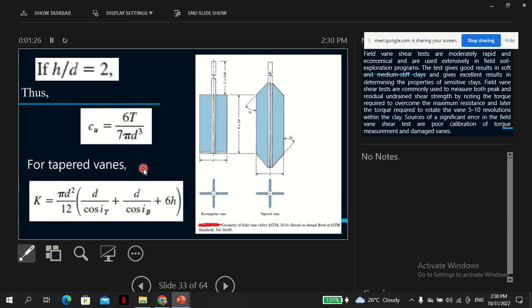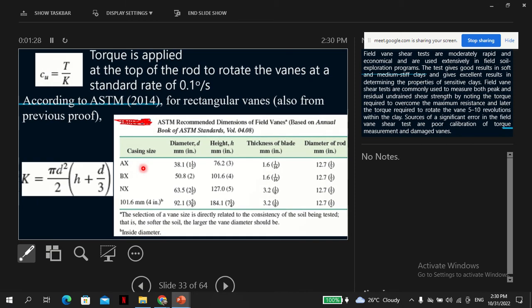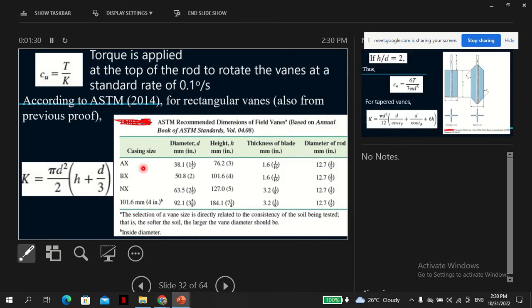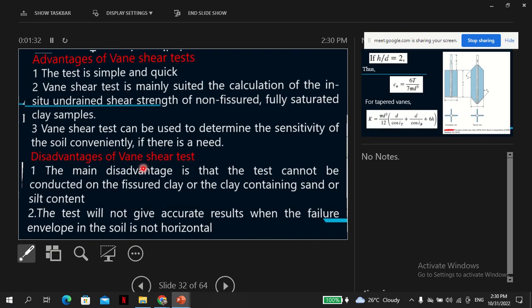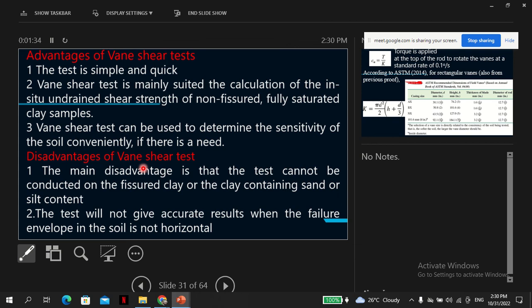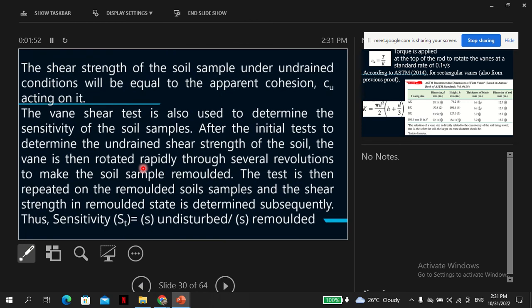Yeah, because for the torque, it uses some correlation to get the torque. You cannot imagine that it's measuring torque directly. Of course, the torque uses some scale, so the calibration process sets some scale to show, okay, maybe 1 unit shows a certain amount of torque. So if that is not done accurately, that is a source of error.